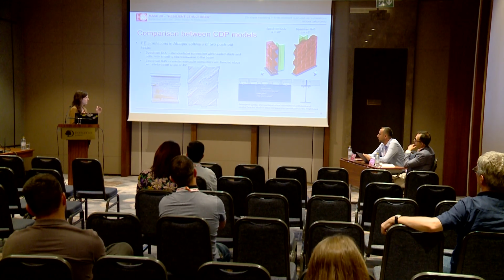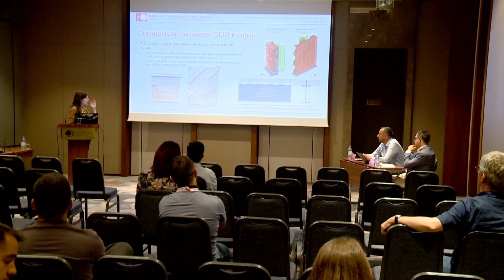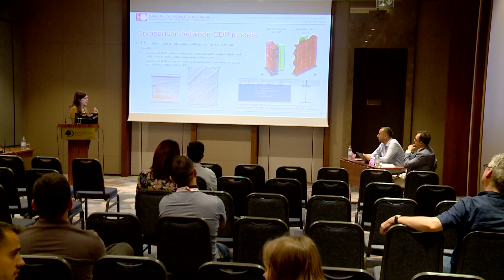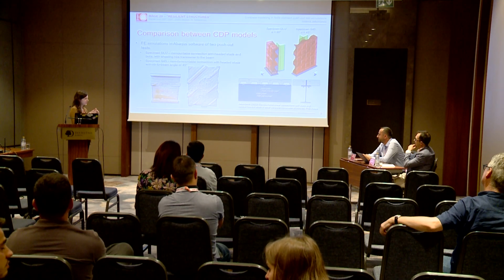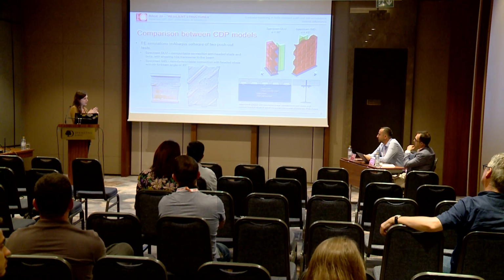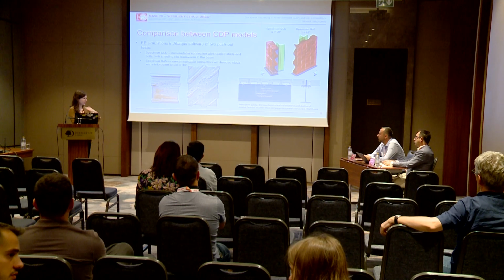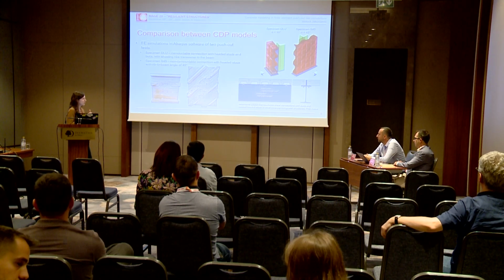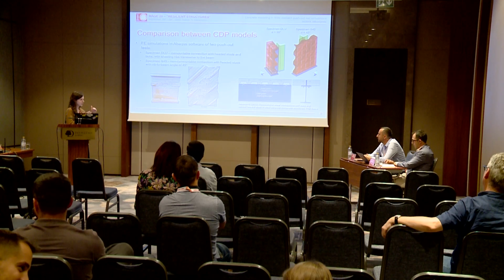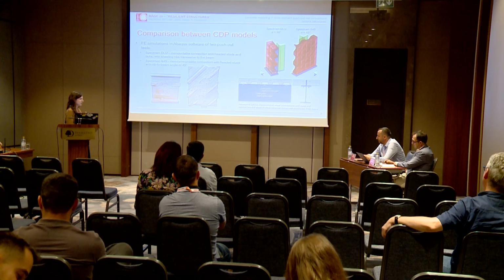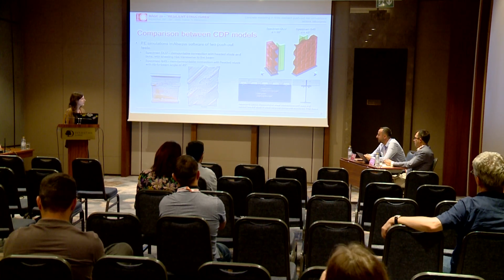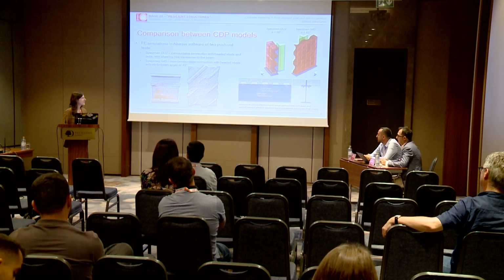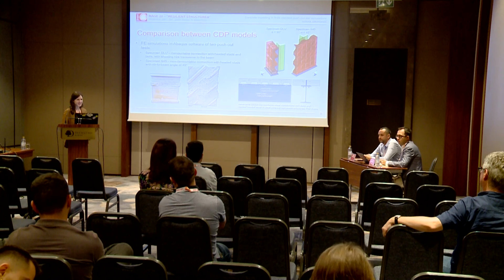Well, the most important was to define that hard contact in the normal direction, so that one material does not go into the other. And I used a tie constraint to model the welded connection between headed studs and the steel profile. So that's something that is mostly used in this kind of tests. So it's nothing new, I would say.